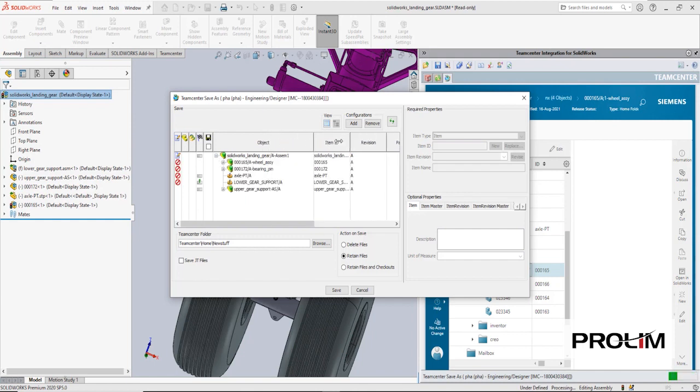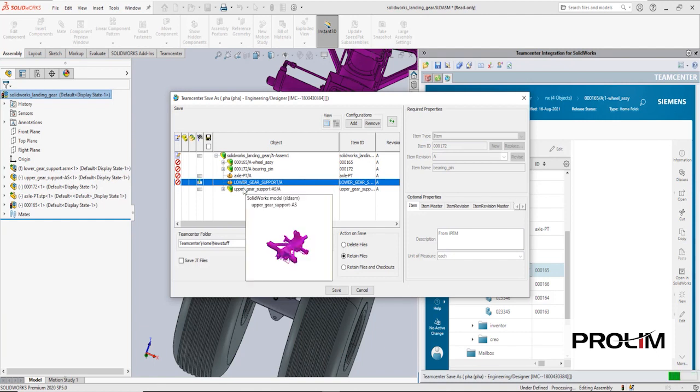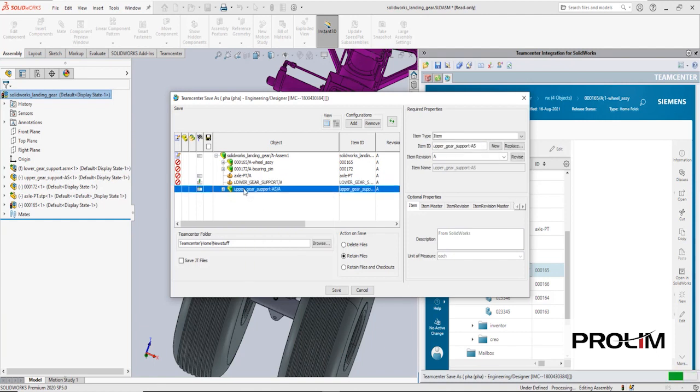From top to bottom, we have a top-level SOLIDWORKS assembly, a hybrid NX subassembly, an indirectly used, through JT, Inventor subassembly, an indirectly reused step file, a directly reused Creo subassembly and a native SOLIDWORKS subassembly. Only the native SOLIDWORKS models may be saved to Teamcenter.